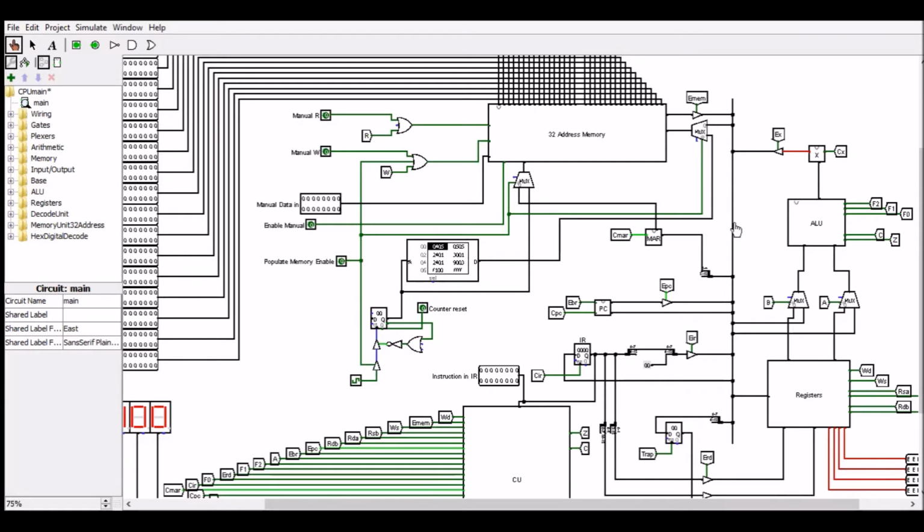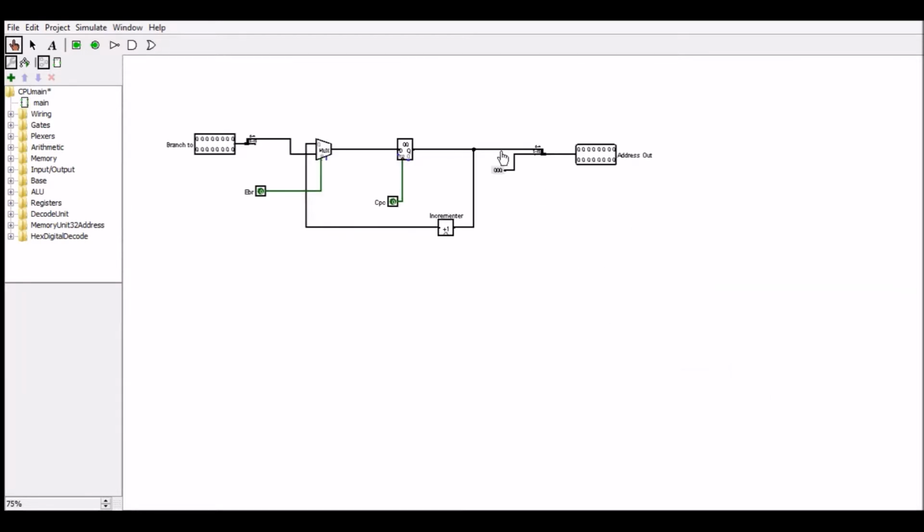They all have to be 16-bit. Because we have 32 memory addresses, the memory address being transferred will be 5-bit, but we use filler zeros, as demonstrated here, and bit splitters to add extra bits that will just be 0 onto the memory address in order for it to travel onto the bus. And that's the same when it's being input here as a branch.